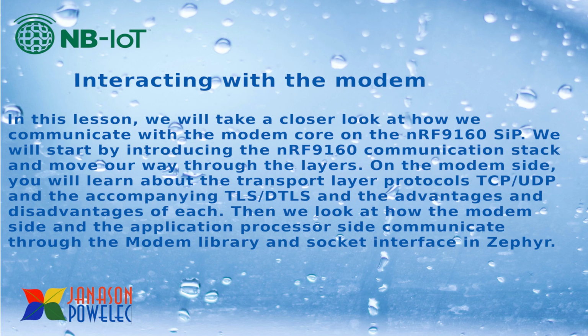Interacting with the modem. In this session, we will take a closer look at how we communicate with the modem core on the nRF9160 SiP. We will start by introducing the nRF9160 communication stack and move our way through the layers. On the modem side, you will learn about the transport layer protocols, TCP/UDP, and the accompanying TLS, DTLS, and the advantages and disadvantages of each. Then we look at how the modem side and the application processor side communicate through the modem library and socket interface in Zephyr.